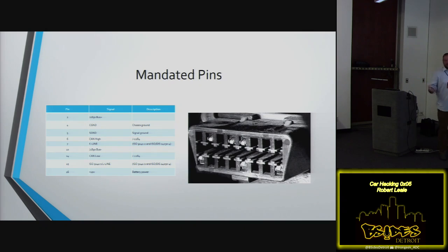There's 2 versions of J1850, VPW and PWM. If it had 2 pins, then we would know it was PWM, I think, off the top of my head. And then this one is essentially GM's version, because GM J1850 was just 1 wire. So that's a 1-wire connector. It has ground here, 2 pins of ground, a chassis ground and a signal ground, and then 12 volts or VBAT, if you will.